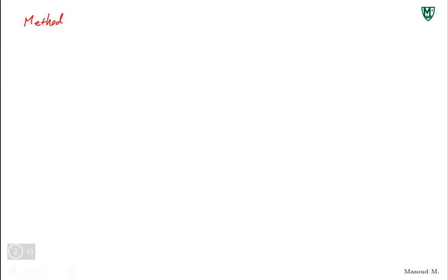Method of sections. So what is that method? Now, method of joints, if you went through the homework assignment, you'll see can sometimes be very frustrating. Sometimes you want to find an internal force or some external force at a specific member, and you don't want to start from the joint that meets your requirement and go joint by joint to get to that member to find that specific, unknown force you're looking for. The method of sections is going to help you a little bit with this.